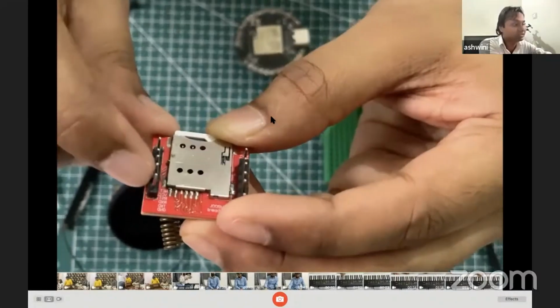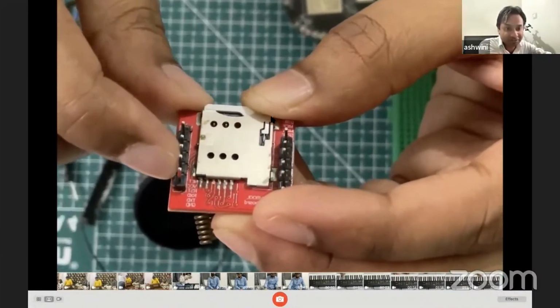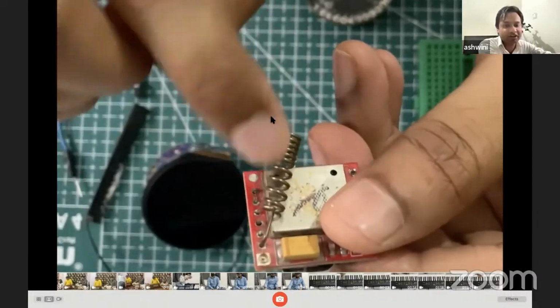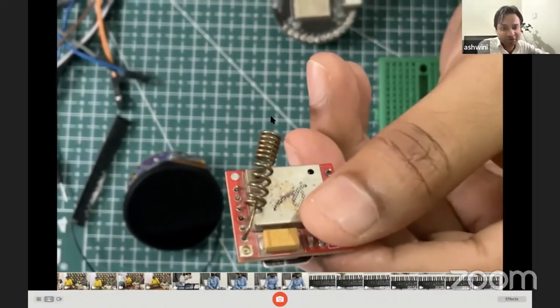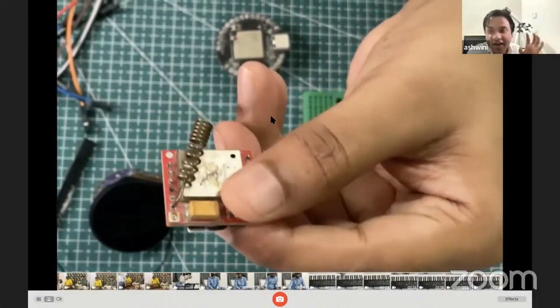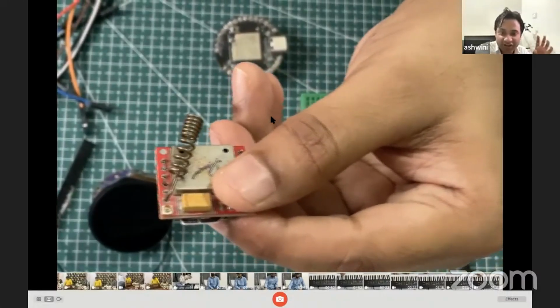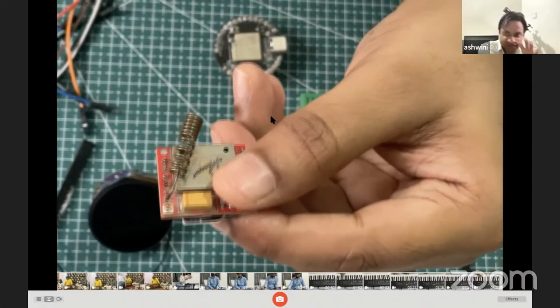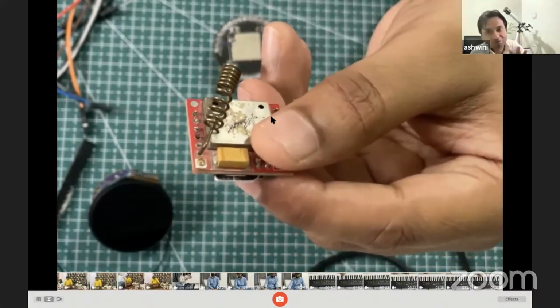And then there is a ground, a VCC pin, and an antenna pin. So we have connected the antenna. You can also connect an SMD antenna using the UFL connector, because most of the antennas you see in a phone are UFL antennas, embedded inside the phone's body.